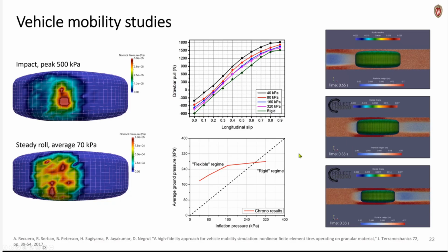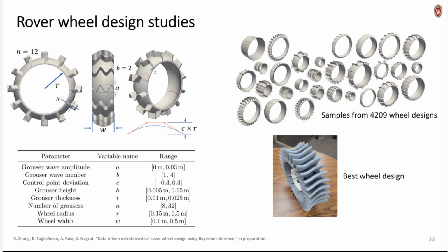So multipass is important when you have a convoy, because the second vehicle will always evolve in the deformed terrain, on the ruts that were generated by the first vehicle. But even for a regular vehicle, the rear wheels do not see the same terrain as the front wheels, right? Another thing that you can do if you have this capability is use it to optimize design, right?